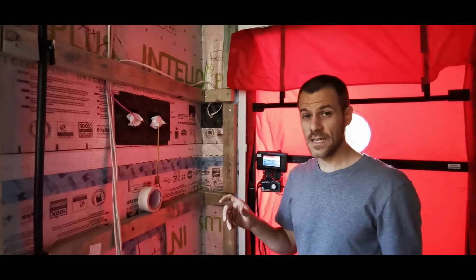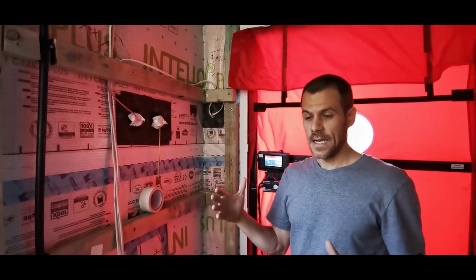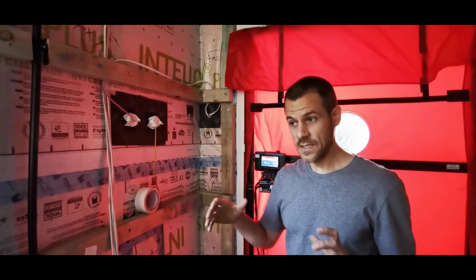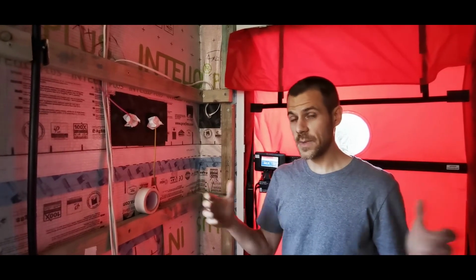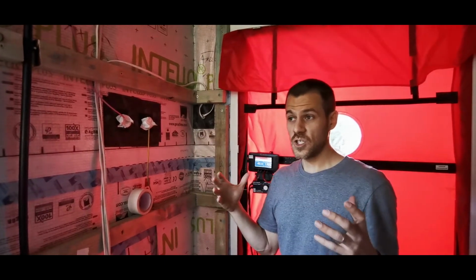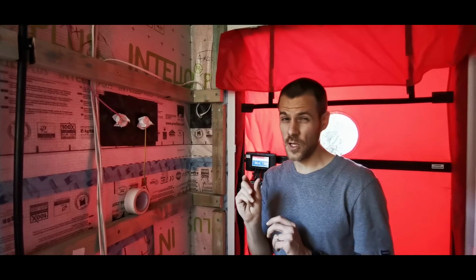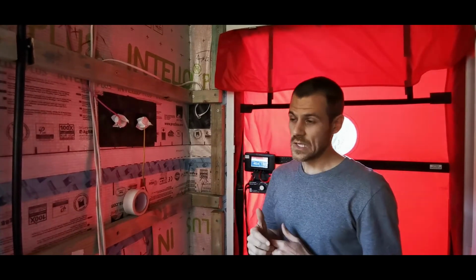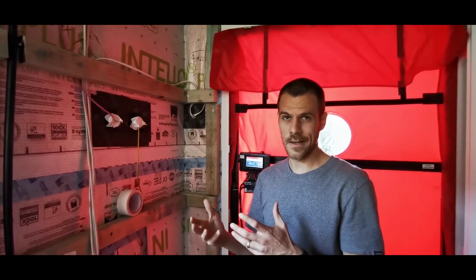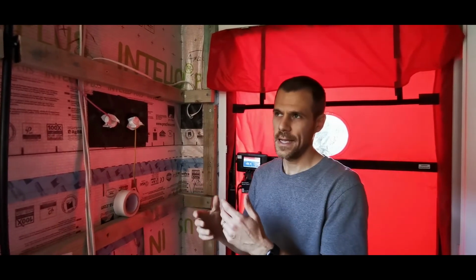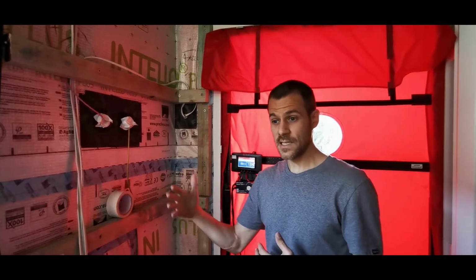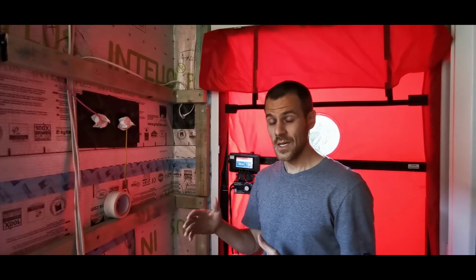With passive houses, because they're so airtight, you have to really be gentle with the fan pressure. If you turn it up too fast, there's not a lot of air leakage coming in to replace the air that's being drawn out by the fan. So you can change the pressure in the building really quickly with just a little volume of air, a little airflow. So you have to be really touchy. It's almost like an art form, testing a passive house, because it's pretty unforgiving. Also, things like wind have a really big influence on the pressures.